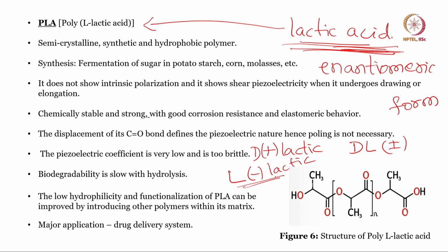This poly L lactic acid shows intrinsic polarization property, and that is why we need not process this material by any other techniques such as elongation or compression in order to improve its piezoelectric behavior. In polylactic acid, the piezoelectricity is a result of displacement of the carbonyl group present in the polymeric chain.